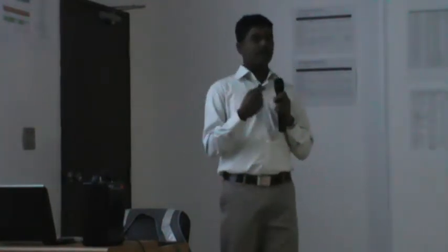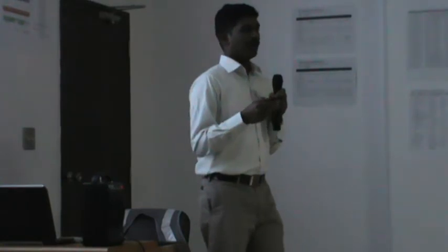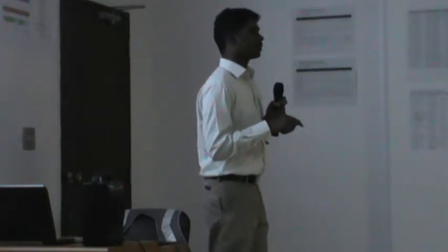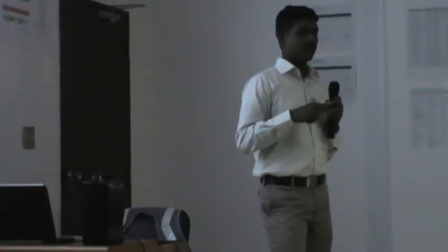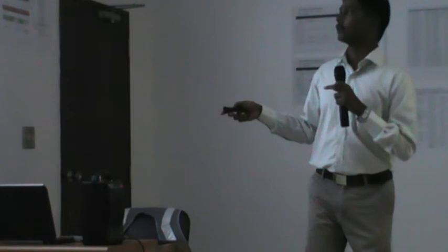So these are the PA instruments, and the DP will be all your motorized valves and the PLC communication. The DP cable, the decentralized peripheral cable, is used for all your motorized valve communication and the PLC communication. The motorized valves will be communicated in a loop. The cable is communicated in a loop. It will go and come back to the DCS, and in between all the devices will be communicated.